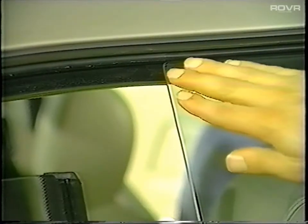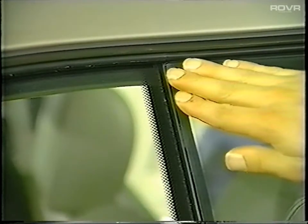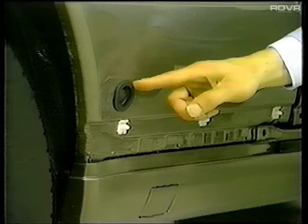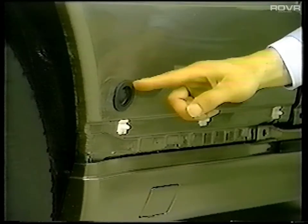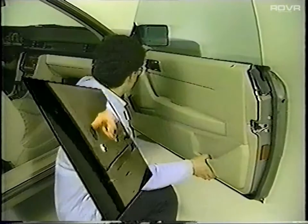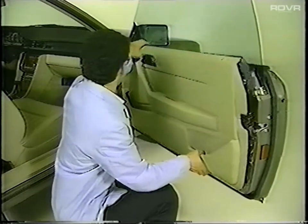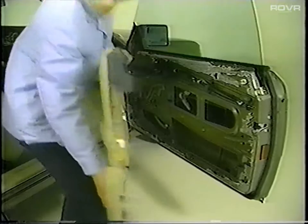Looking at the rear glass, the window must seal properly, but not so tightly that it pushes the door glass out at the top. The rear window tension is adjusted in a similar manner. Next, we will look inside the door. After removing the familiar hardware, the interior door panel is removed by lifting up.